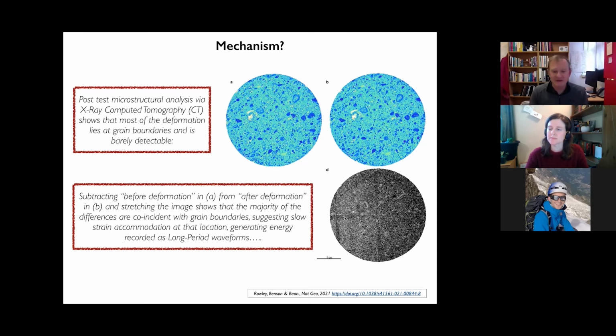But you're right, we don't have sensors which are calibrated in absolute terms so much. That is changing. There's new technology and new sensors where we have a faceplate calibrated for velocity, but most of the AE data is uncalibrated voltage, and therefore qualitative comparison is more common than quantitative comparison. But I guess watch this space again. Things are slowly starting to change as the technology improves.